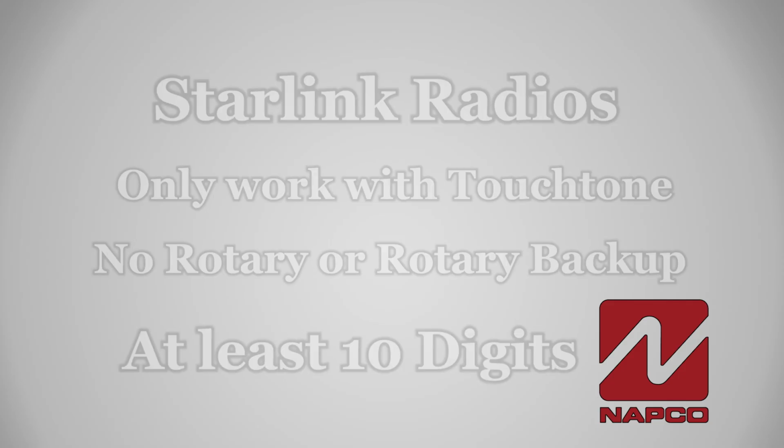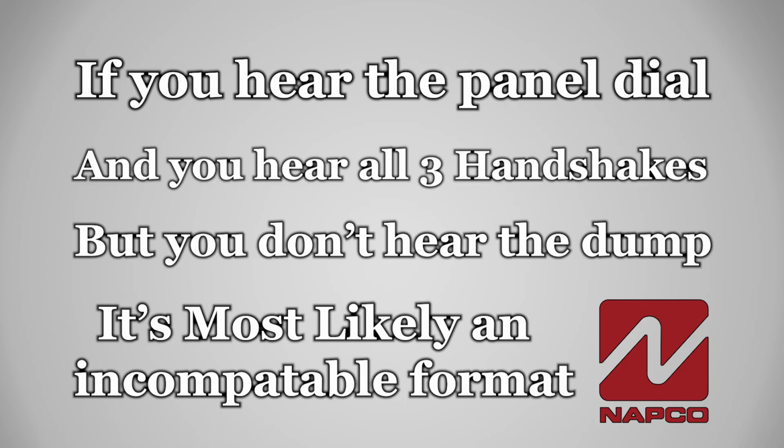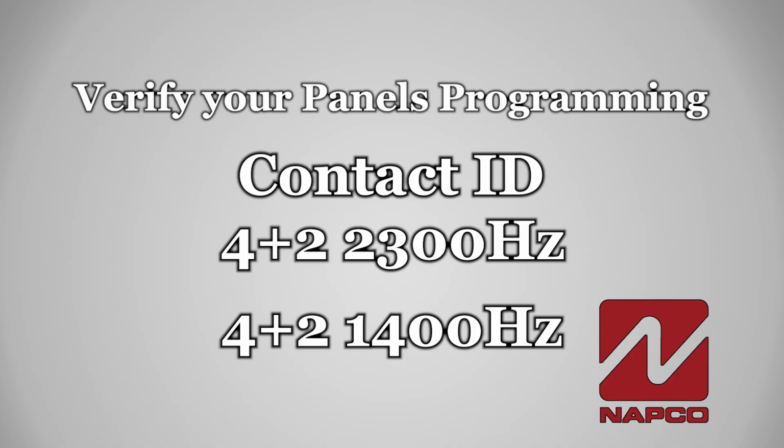phone number. If you hear your panel dial out, and you hear all 3 of the handshakes, but your panel does not respond with a dump, your panel is most likely programmed with an incompatible format. This is what I have found to be the most common problem. Often people will guess or just go on what someone else has told them about the panel central station format. Verify the central station format in your panel's programming. Check and make sure your panel is set to contact ID or standard 4x2, either 2300 Hz or 1400 Hz.